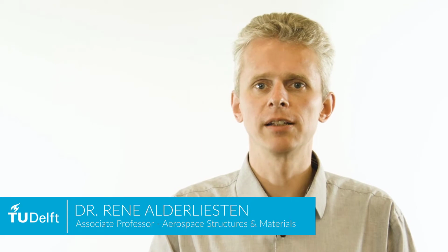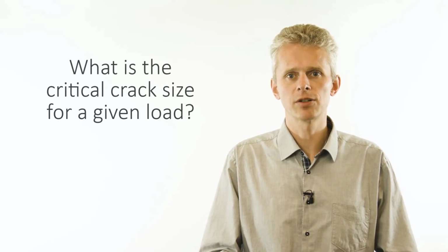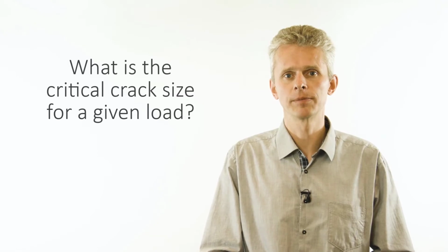Damage-tolerant analyses have the objective to determine up to what extent a structure is tolerant to damage within the structure. Take for example fatigue cracks. The question then will be at what size of the crack a structure will fail under given loads.